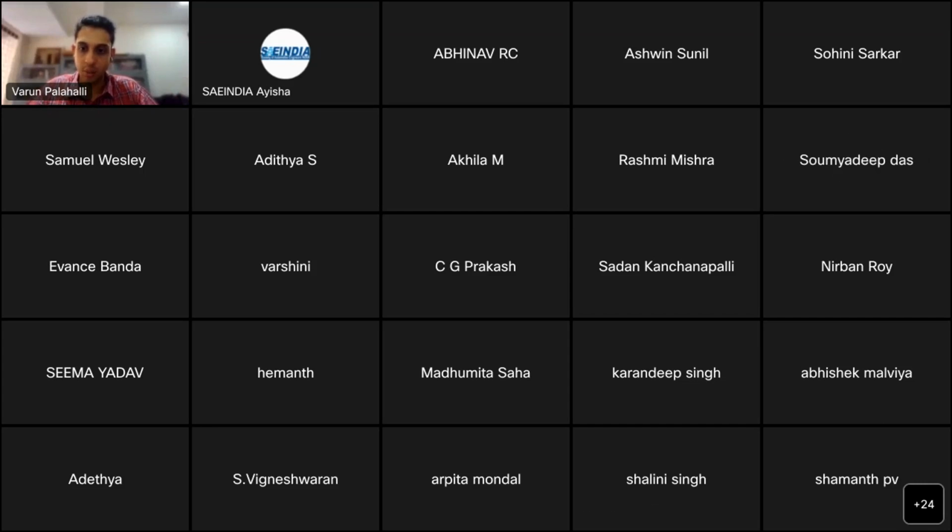Abhinav has posted a question saying, what is frequency modes in modal analysis? So just to answer that question first, what modal analysis does is that it gives you the natural frequencies of your structure. For any continuous structure, you have an infinite number of frequencies. It's unlike a discrete lumped body. This is something that you would be able to appreciate in mechanical vibration. So modal analysis gives you the natural frequencies across the range that you set.